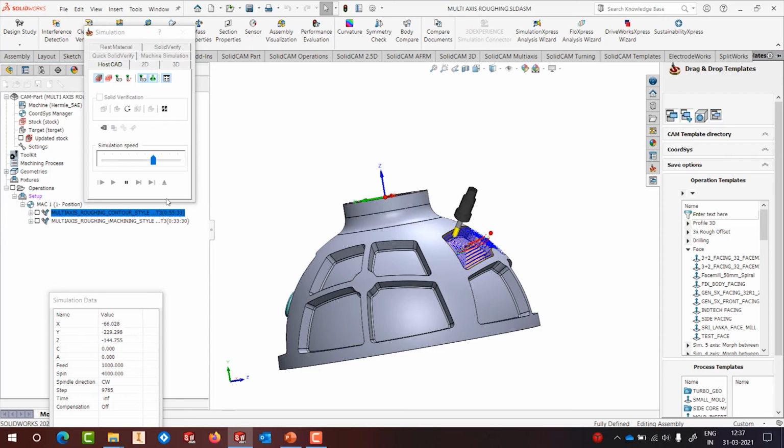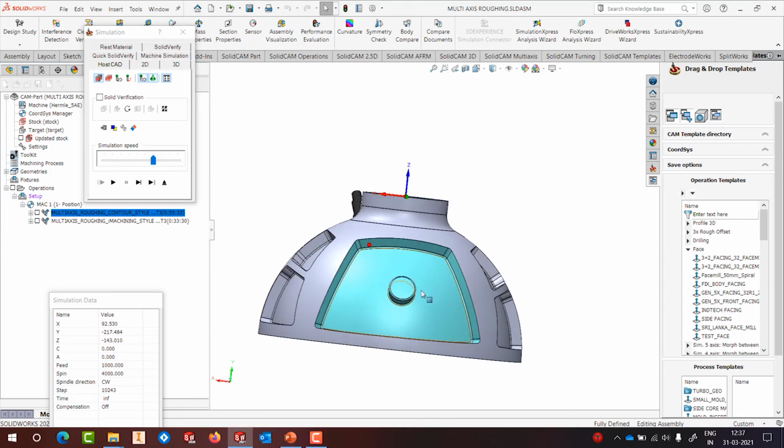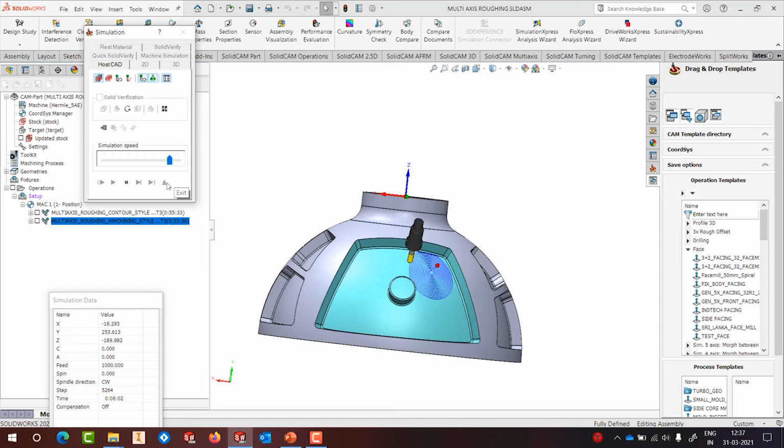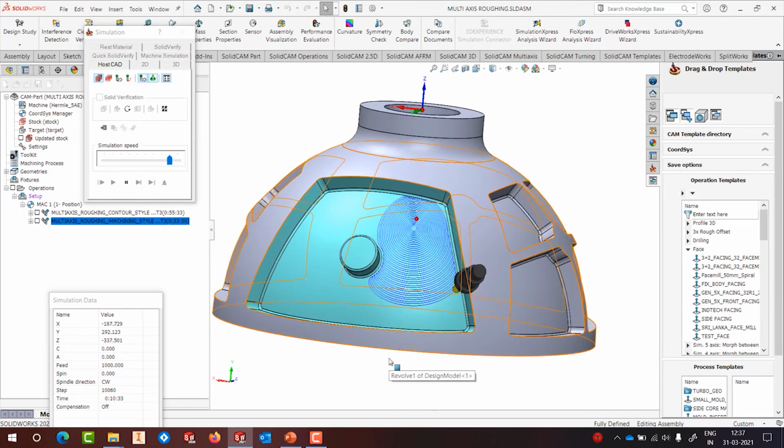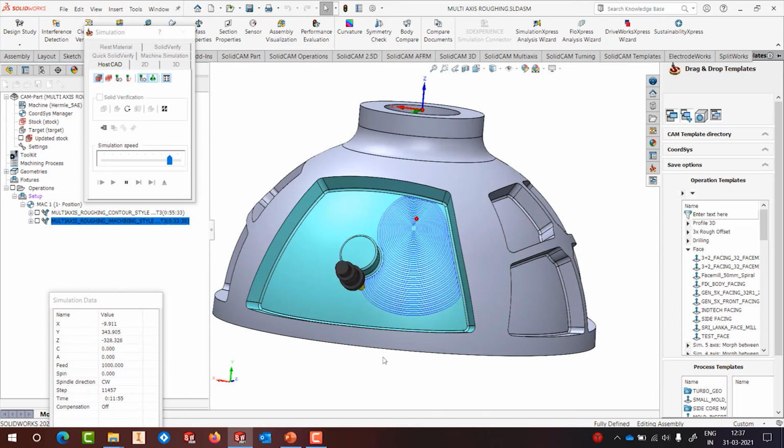this geometry. In areas like this, we could also use what we call the adaptive strategy. It has a look and feel of iMachining, where we maintain constant cutting load on the tool, uses similar principle, and we can machine this part using the adaptive strategy in full 5-axis. So parts like these can also be easily handled inside SolidCAM.